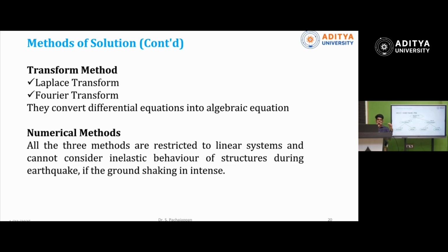In this free vibration, further we are going to have damped free vibration. Damped free vibration means a damper is installed in this beam. If the damper is present here, applying the initial displacement, then it is going to vibrate. After that, it will come to rest because of the damping present in the system. What is damping? It is a force acting against, or opposite to, the motion. So, a damped system is there, and an undamped system is there.